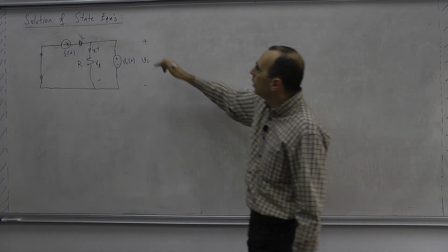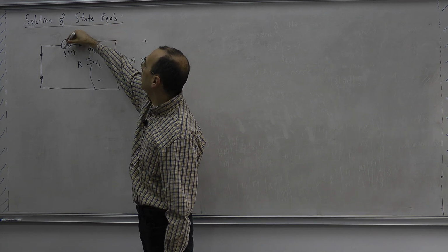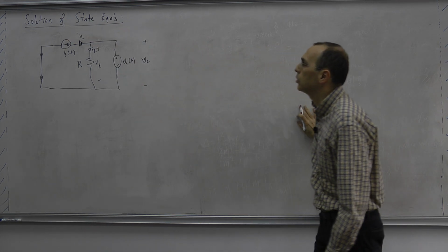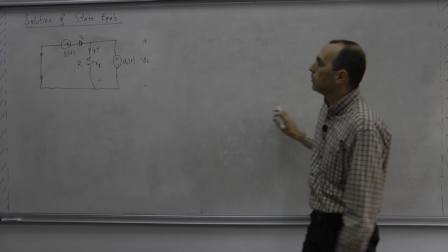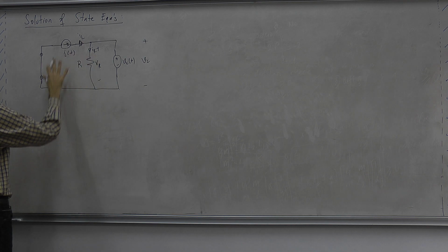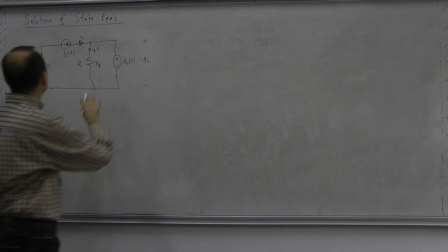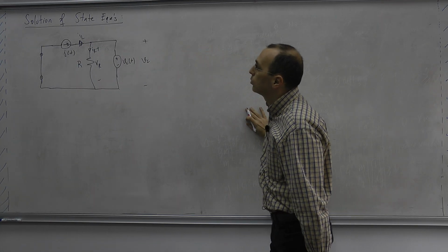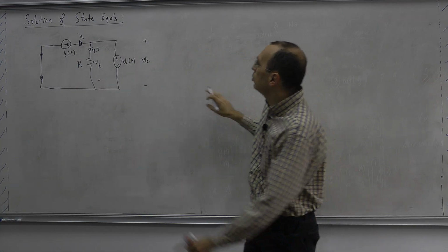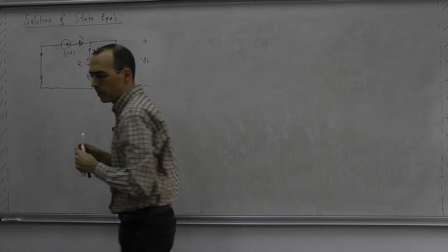So what does it say? Any other variable, IR, is dependent on IL and VC, our potential state variables. So we see that we have two independent state variables, okay, and any other branch voltage or branch current can be represented by simply an analysis of a memoryless circuit as soon as we find these values or the functions for these state variables.